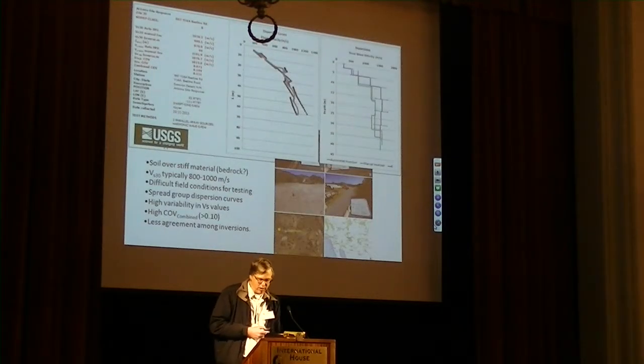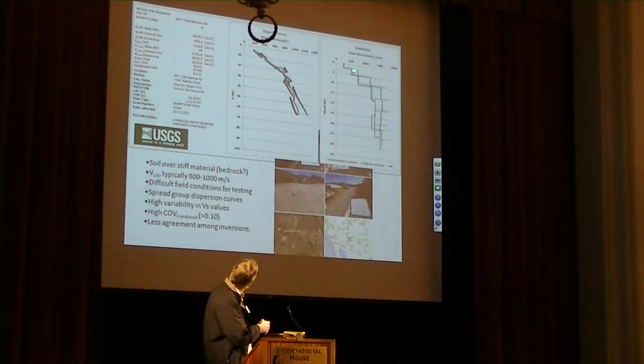There's a rock site that came out, so this is the same thing, shear wave velocity here, depth, and now this goes higher, and you're getting up over 1,000 meters per second. Velocities below 10 meters. So now we're seeing a shallow soil over rock.